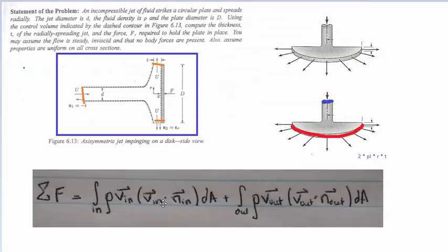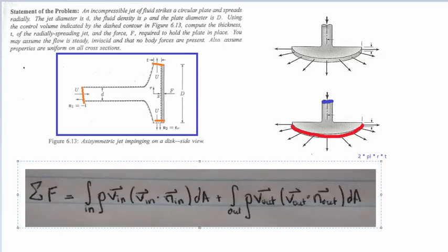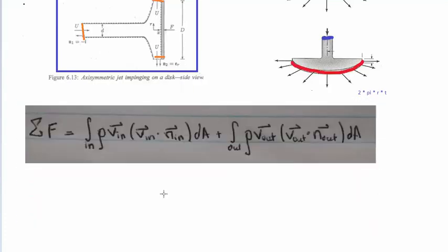Again, that looks like this. Just the external forces on the left, and the surface integrals on the right. Because again, I'll say it again, what are our assumptions? Flow is incompressible, steady state, and velocity profile is constant. That means that after we've done these dot products, we could simply pull rho and v outside the integral and just integrate over dA.